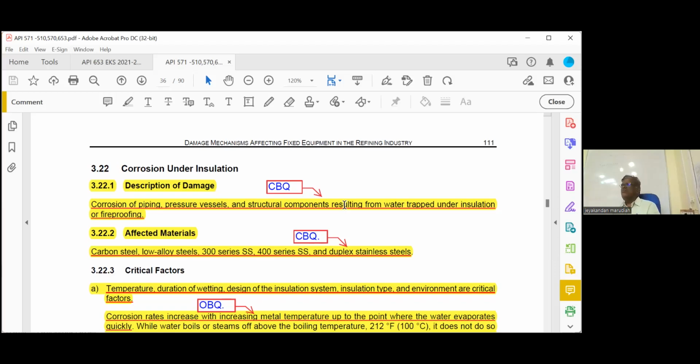There is one corrosion called galvanic corrosion. That is cathodic protection basics. Aluminum will corrode and protect the steel. Or for stainless steel, we can use the aluminum foil and insulate it. Okay, these are how to prevent it.